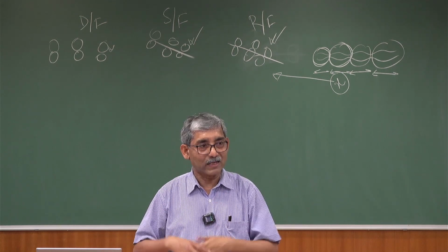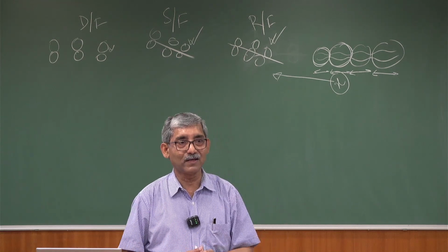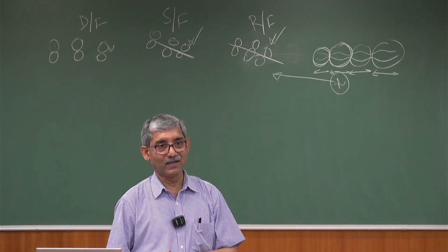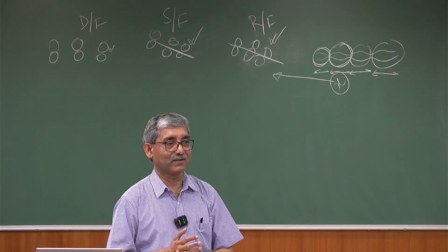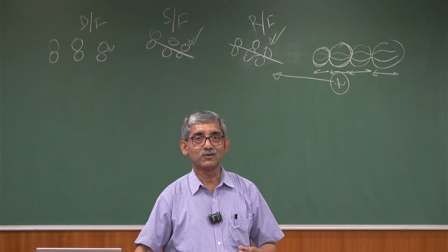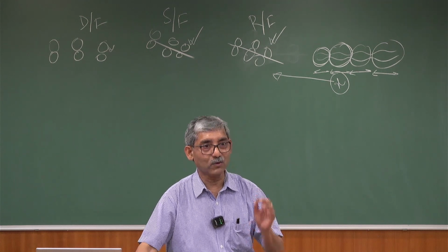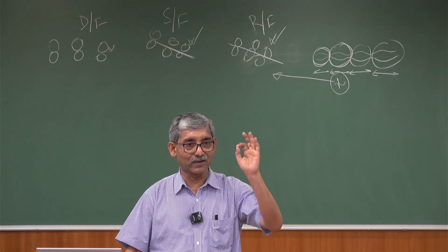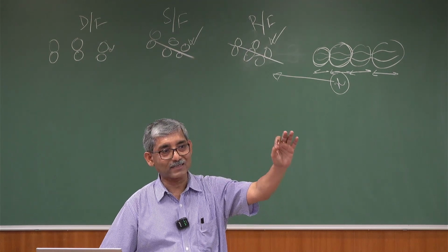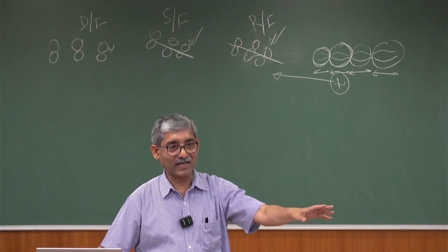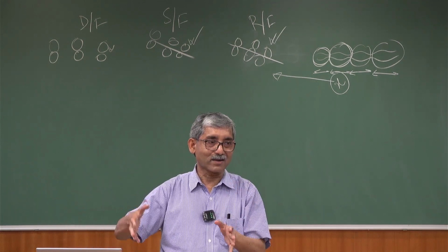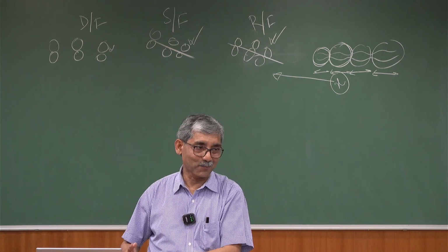So you are investing more money to produce the same quality and quantity. The quality of 20 centinewton per tex is better than 10, but our target is to produce 10 centinewton per tex.